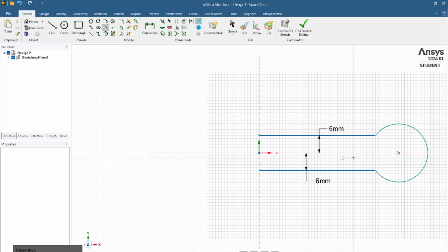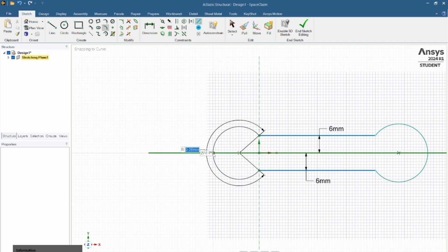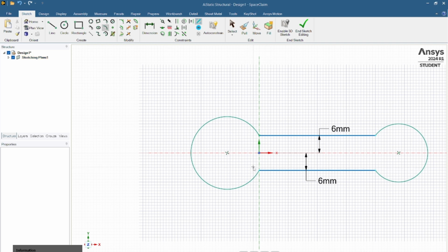Okay, now another 3-point arc, click on the vertices and now enter 12.5. Here you can see our circles are created. Now just escape to remove the selection and now select polygon. You can change sides accordingly, whether you need 6 edges, 8 edges, 7 edges, according to your need. Now click on it and put the diameter, it's 12. Enter. Here you can see this is created.